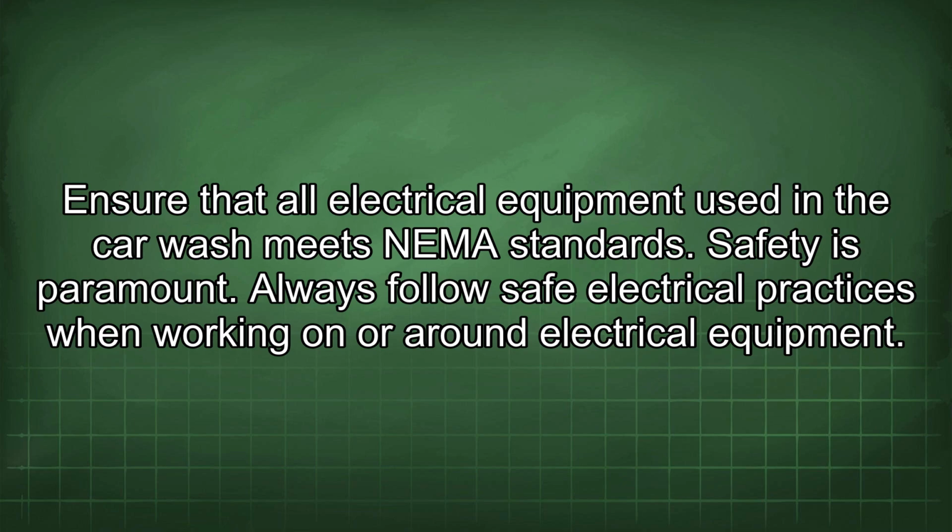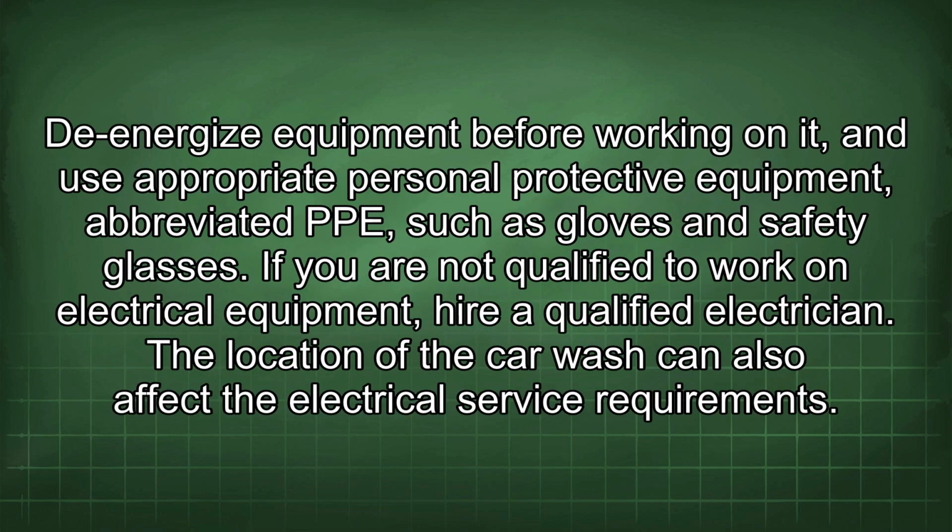Safety is paramount. Always follow safe electrical practices when working on or around electrical equipment. De-energize equipment before working on it and use appropriate personal protective equipment, abbreviated PPE, such as gloves and safety glasses. If you are not qualified to work on electrical equipment, hire a qualified electrician.